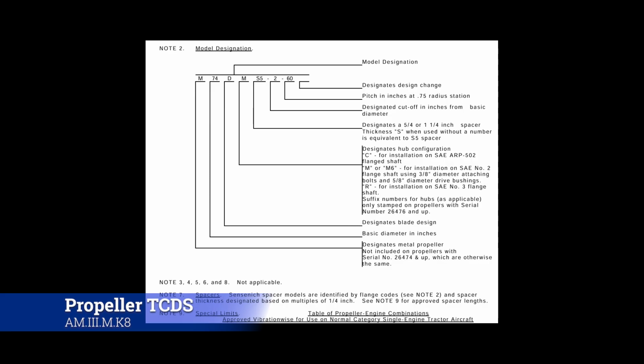The notes are usually what will get you, because there'll be some random note, like, if you have this number or this number, then don't use this type of bolt. This is especially true with your O&Ps. I'll tell you, the IA test is the big gotcha section where they will try to trip you up inside of the notes.